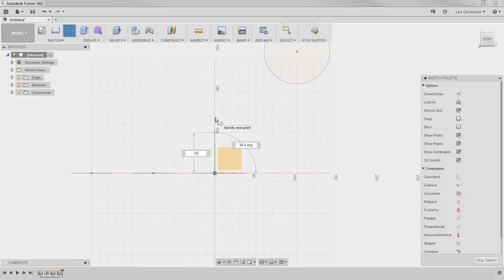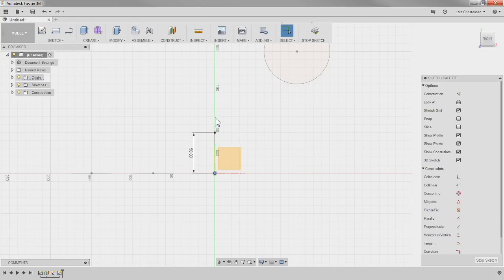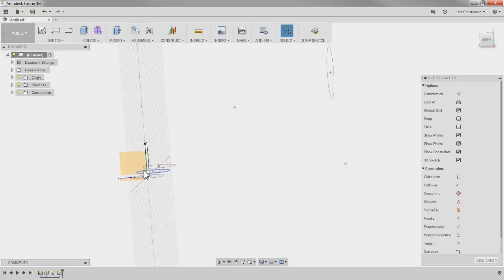Now hit Tab on your keyboard and notice how you get a lock next to the vertical, the 50. And then see how the 90 is now highlighted, so you could actually change the angle. But if I just hit Enter again, then it will lock it in and you get the 50 and the horizontal relationship. If you don't hit Enter there, then you don't get the relationship. All right, so this is just a straight up line coming right on that plane.